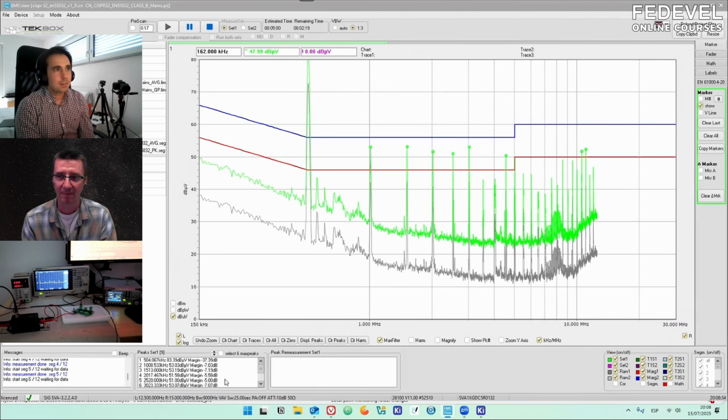So I understand now. Oh, okay. So basically, this can really help. This very simple setup can really help with measurements, and you can also see the fixes. If you fix something, then this frequency will not go out through the cables. That's the idea. So this setup with the near field probes can really help you to pass conducted emissions the first time, and to avoid so many back and forth trips to the lab: pack everything, make the test, come back. Which is time consuming and expensive, because every day in the lab is expensive.